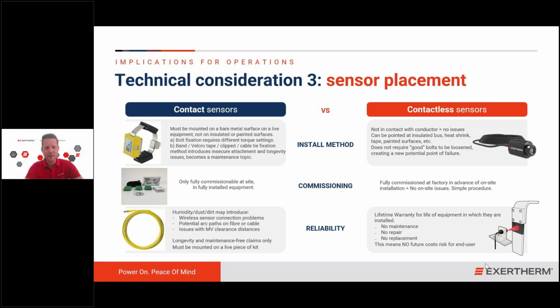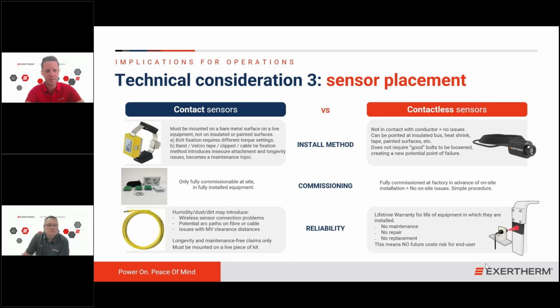Well, if the energy harvesting sensor loses the connection, it powers down and doesn't communicate anymore. And eventually, you're going to have to go there and restrap it in order to have it fire up again. Or even worse, what if the cable tie, due to vibration or temperature, or whichever externalities, finally loses connection and just drops inside the power equipment into one of the power compartments?